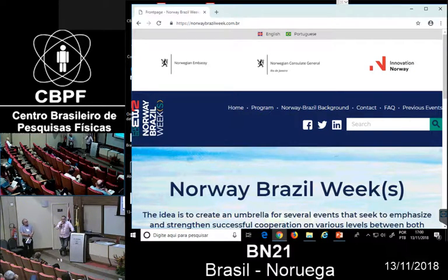Lula field produces 220 barrels of gas for each barrel of oil, and 40% of that is CO2. So the most logical option for them was to do WAG using a CO2-rich flow of natural gas reinjected in the reservoir. But the future idea is to separate the CO2, export the natural gas, and reinject only the CO2